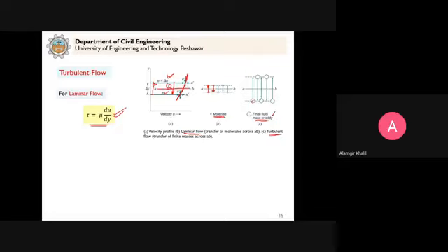So rather than molecules, as in case of laminar flow, in this case these pockets of fluid move from one layer to another layer. For example, from this lower layer, this eddy will move into this layer. And similarly, from this layer, it can move to this layer due to turbulence. And as a result, when an eddy comes to the next layer, it can merge with another eddy, and it can grow in size, and so on.